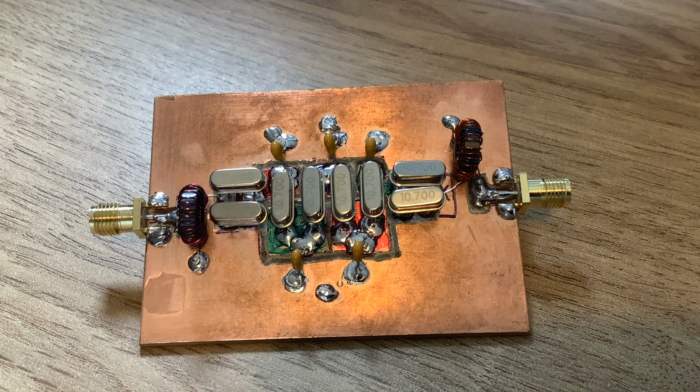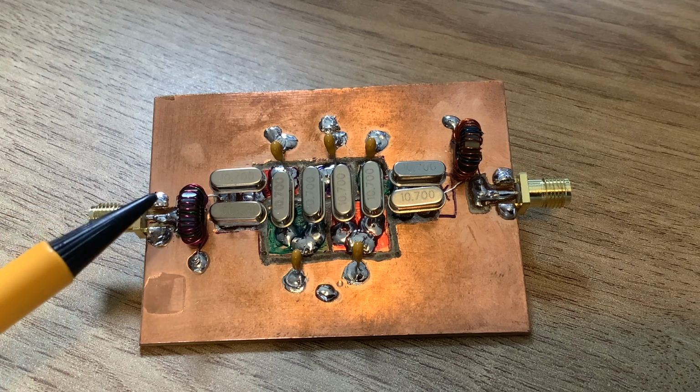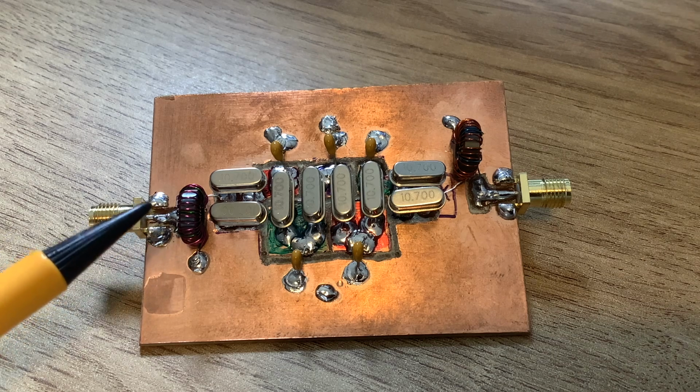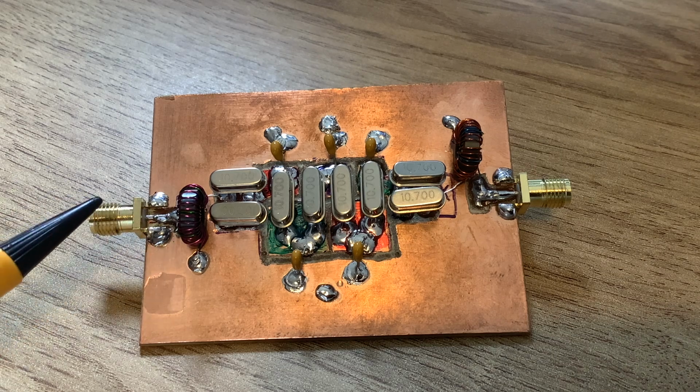Now, to find out the turns ratio, you have to take the square root of that. So the square root of 24 is, well, 4.8989, etc. So let's call it 4.9. Now, I know that in order to get the required performance on the primary here, I need to see 4 or 5 times the impedance hanging off it.